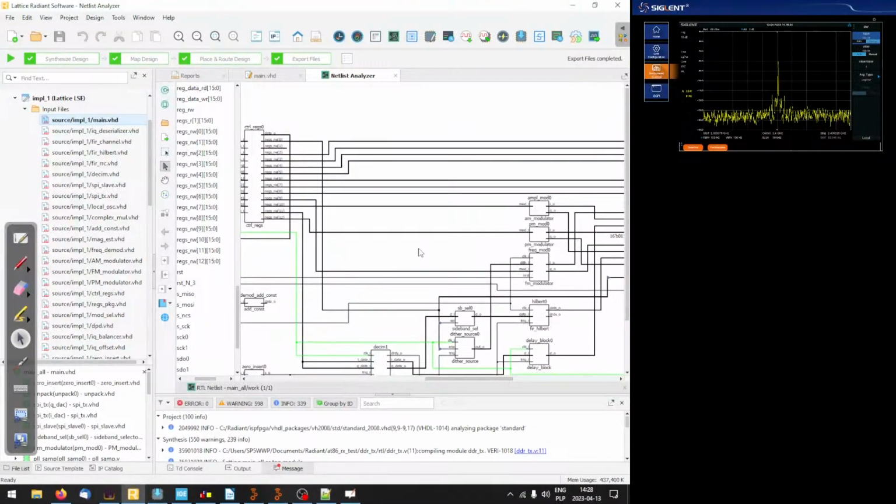Yeah, so compared with the speech signal in the analog FM, the CTCSS takes about, I believe, 10 to 15% of the signal. So it's not very strong. It doesn't have to be strong to be detected at the receiver.